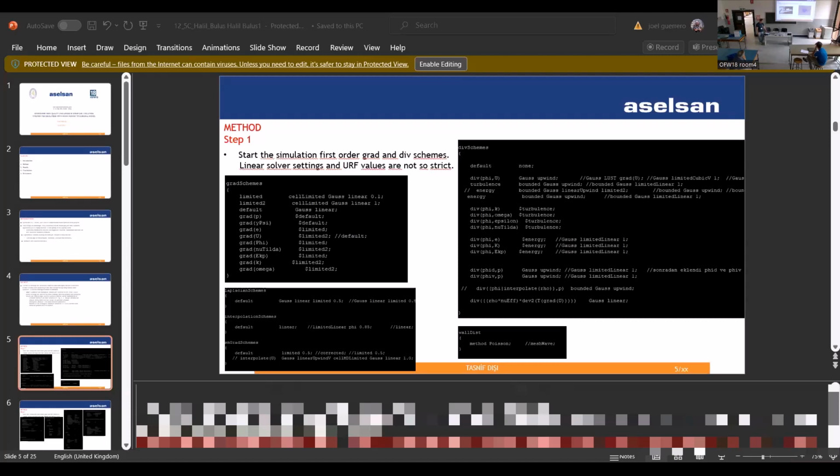It has a total of 4 million cells. Also, I want to mention that this experiment has a Reynolds number of 100 million, a Mach number of 0.84, and an angle of attack of 3 degrees. You can see from the residual iteration graphs that each step that I'm mentioning is changing the values. As you can see, at the end you have to use the second order schemes because the results are changing, if you see the forces graphs.